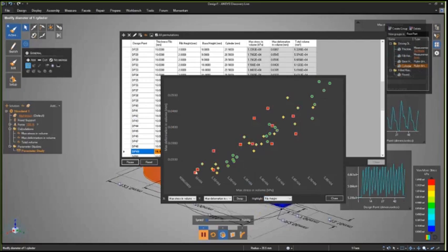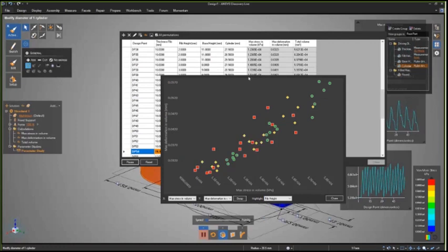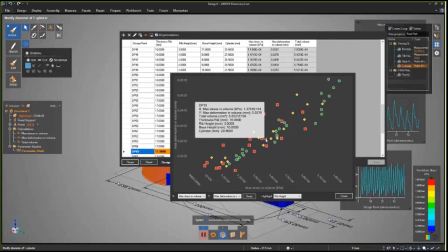This gives me a much better idea for the model I should send through typical Ansys solvers in order to validate. The thing with Discovery Live is it is not meant to validate. If you have one design and you want to know if that design is going to fail, you do typically want to use Ansys Mechanical and Fluent and Workbench and the typical legacy products. If you're trying to rough out ideas and compare a few different ideas to each other, that is where Discovery Live comes into play. I can go ahead and see what this design point is.